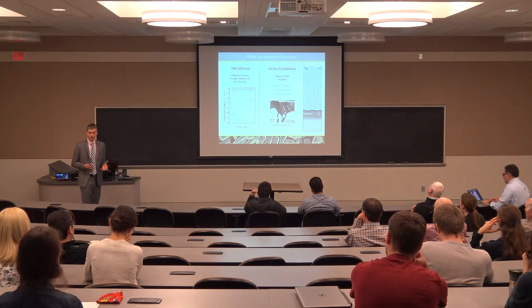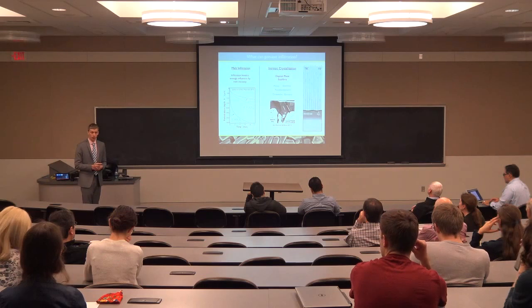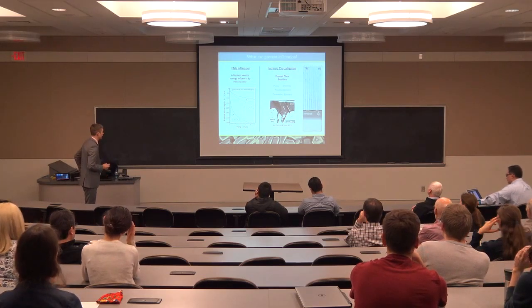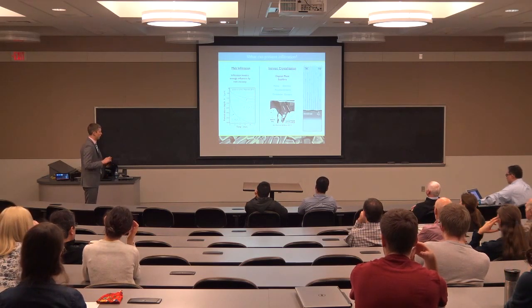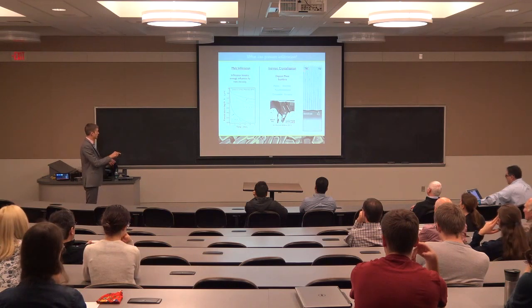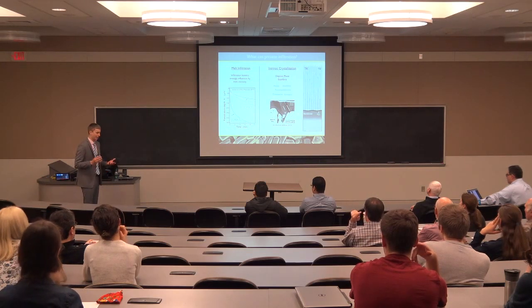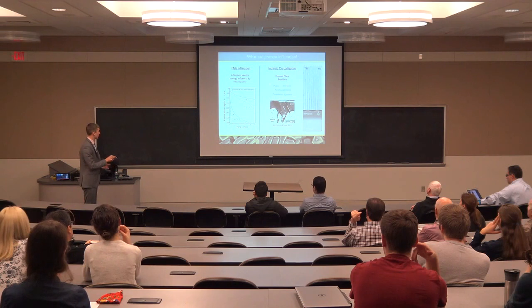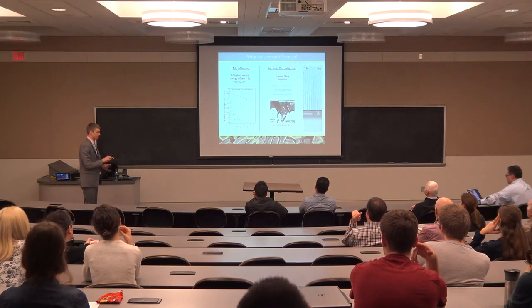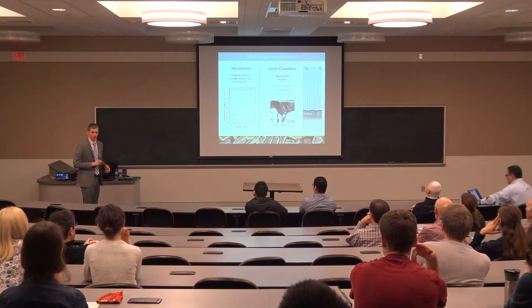So how can we prevent infiltration? For the conventional material, this YSZ or yttria stabilized zirconia material that has long been used in this application, there isn't a lot of interaction between the coating material and the melt. And so the only hope of preventing infiltration is the fact that we have a steep thermal gradient through the coating. And we might hope that as the melt penetrates, it will drop below its solidus. And if the nucleation is fast enough, we might crystallize the melt for some of these phases. These are all mineralogic or geologic type phases, and that might block the penetration.